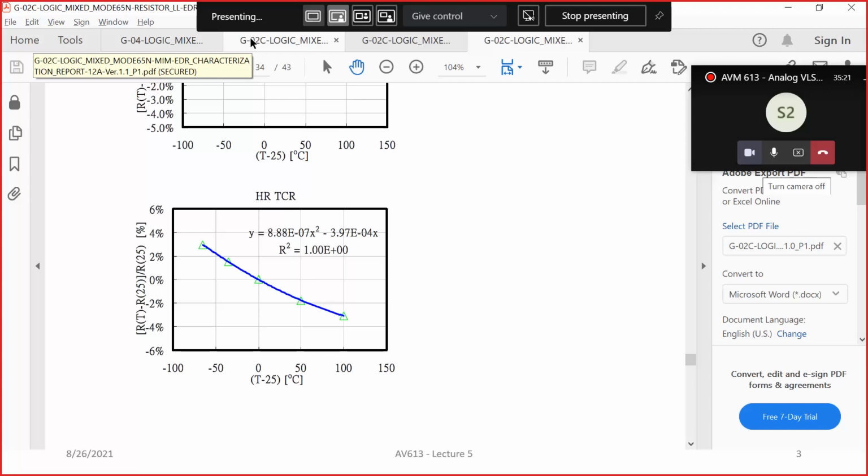Of course, that's a waste of pins, and also it increases your bill of materials. When you talk about designing a product, if you have everything integrated on a single chip, then it is much cheaper. Otherwise, you have to buy resistors, you have to buy capacitors, and so on. Of course, there are some large values of capacitors for which you have to put off-chip capacitors, but there are a lot of on-chip capacitors that can be used.